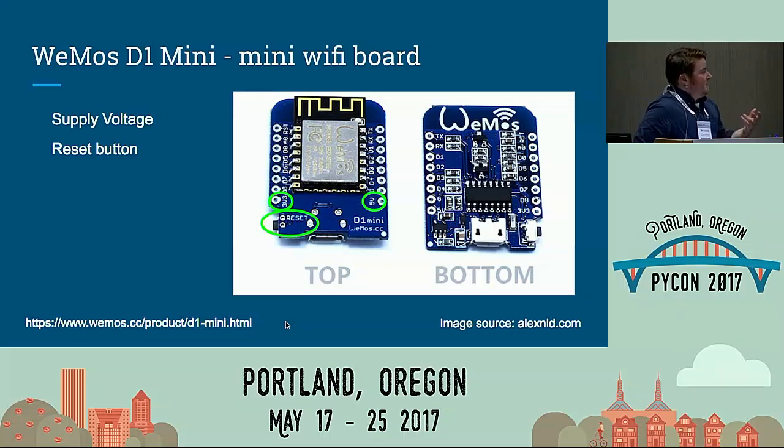For instance, there is a supply voltage pin. You can see there's 3.3 volts and there's 5 volts. In addition, we can connect directly to USB. There's an onboard voltage converter that allows us to supply 5 volts, which is more of a standard, and it will step it down to 3.3 volts for us. So that's a really nice thing. You can just plug it in directly.